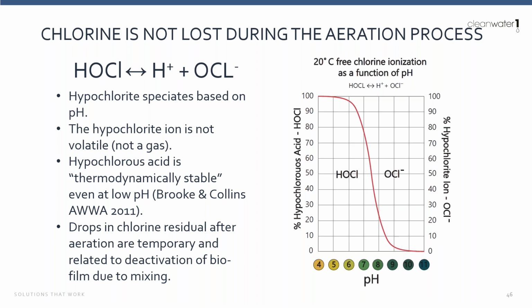However, in the intervening years, I have talked to a couple of different customers, both in the Southwest, both doing THM aeration at large scale, both using chlorine gas as their secondary disinfectant, both reporting roughly a 20% drop in their chlorine residual as a result of aeration. So all the science that I'm aware of says no. I have a couple of anecdotes that say yes, for chlorine gas, we have seen a result. And so that's what I have to report on that. Great question.